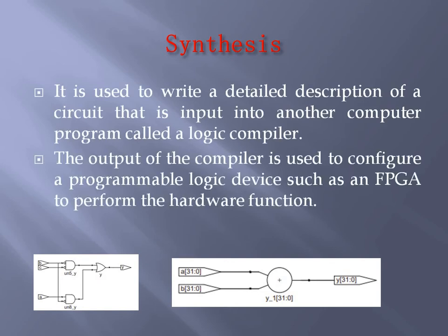Next is the synthesis. Synthesis is used to write a detailed description of a circuit that is input into another computer program called a logic compiler. So the compiler does your compilation, and the output of that compiler is used to configure a PLD like FPGA or CPLD, so that the PLD will perform the hardware function.